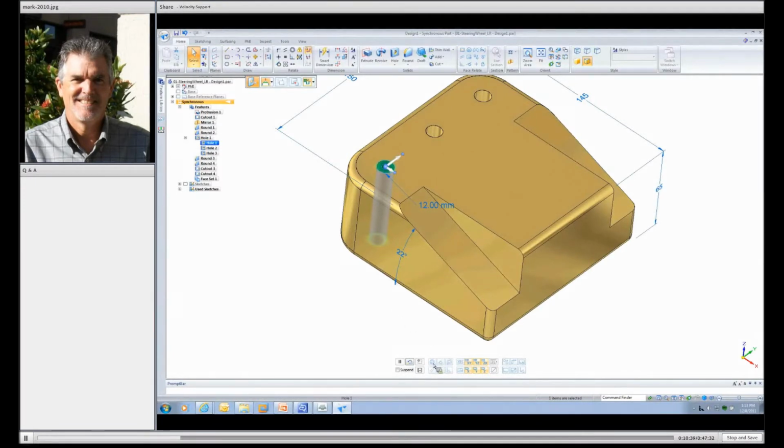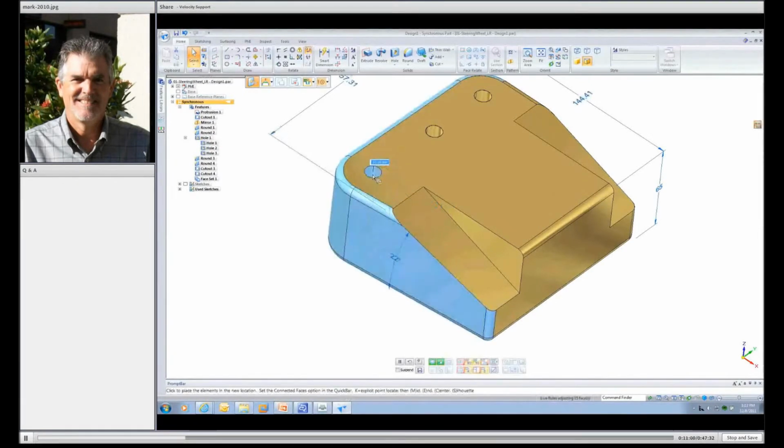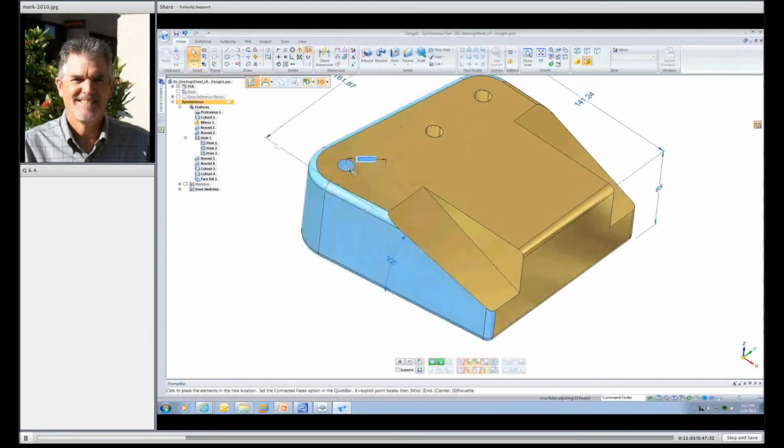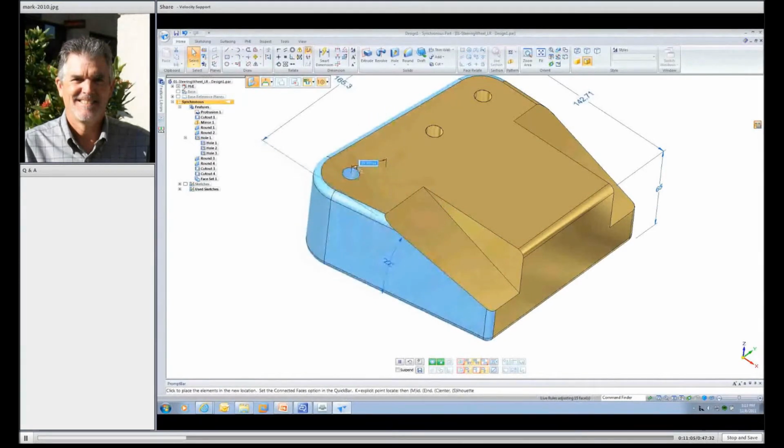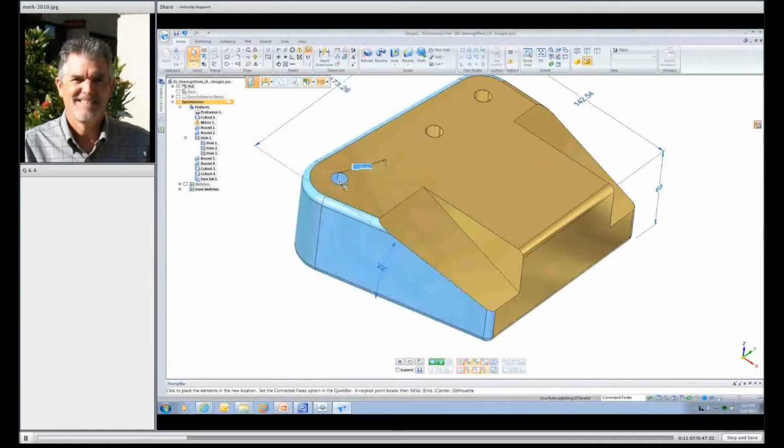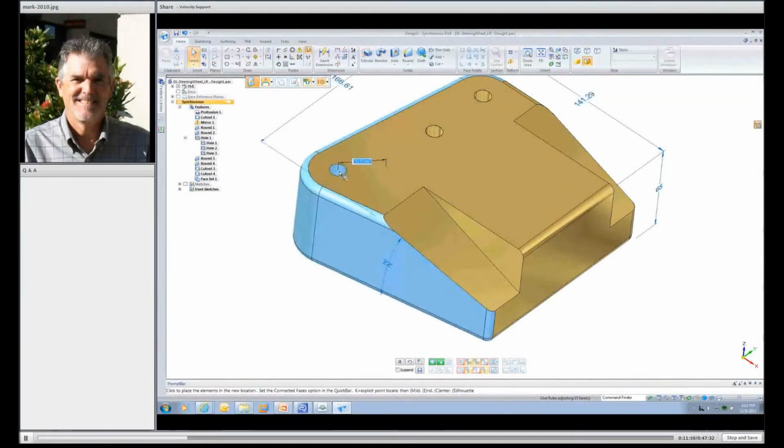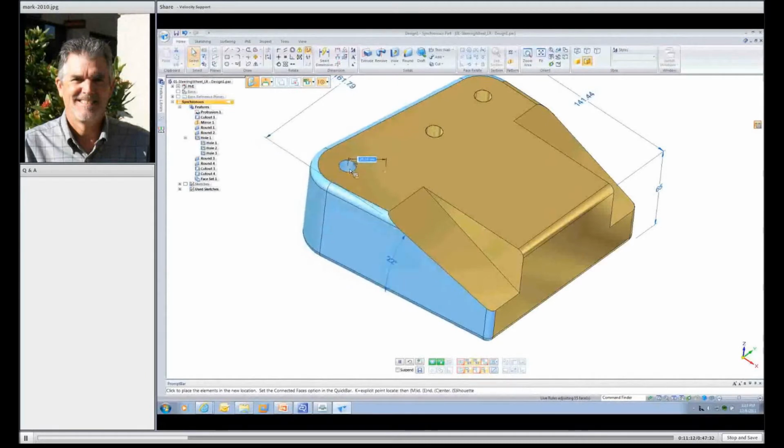You'll also notice that in the steering wheel there's what looks like a blue plane, and if I click on that plane, it's kind of a free-form move, and it allows me to take that hole and simply move it anywhere that I need to move it. And you'll notice that the side faces stay tangent just as you would expect them to do. The other thing that you noticed as I was moving that is the opposite side of the part was not responding. Now again, if I grab that and I start moving it, you'll notice that the opposite side is not moving.